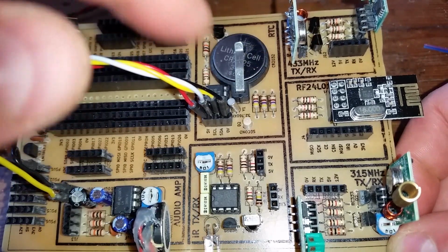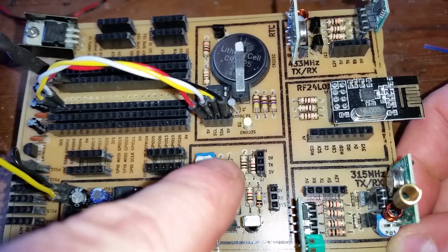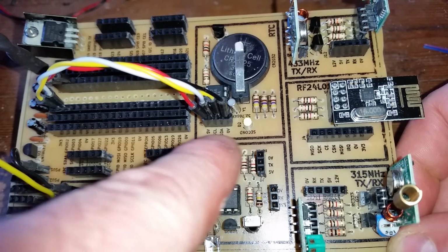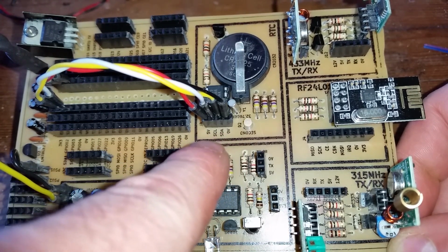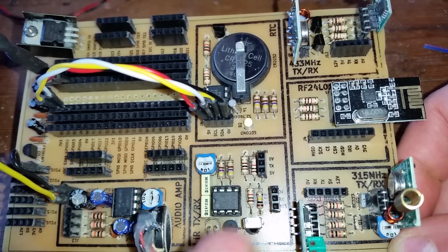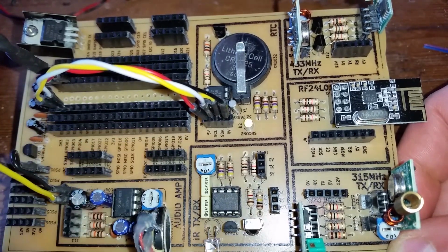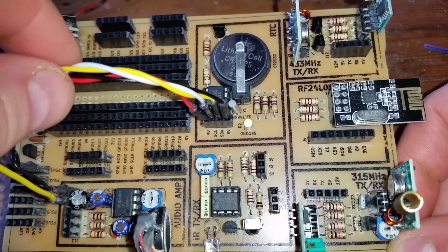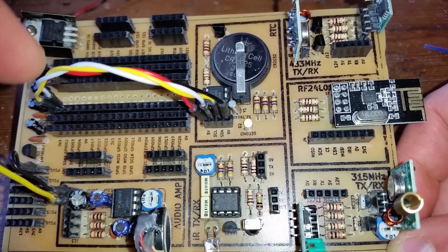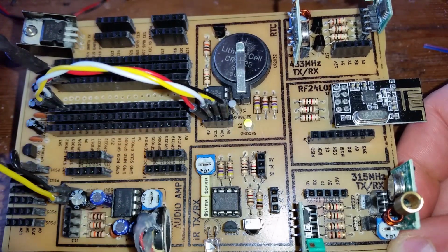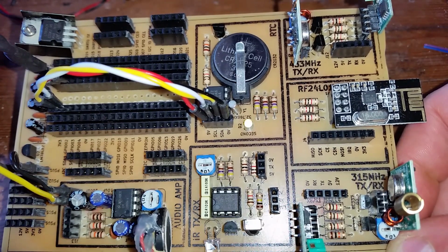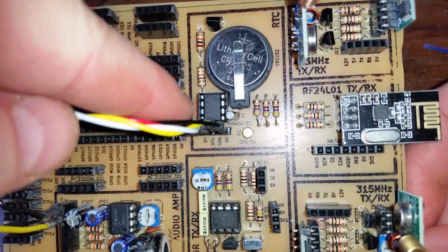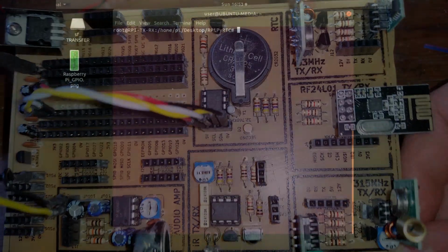The real-time clock part of this circuit only requires 4 connections: 5 volt, 0 volt, and some I2C connectors, a serial clock and serial data. And the serial data is bidirectional, which is why you only need 2 wires to communicate with this. And although I'm connecting to the I2C part of the Raspberry Pi, in Python I'll just be simulating the I2C logic to actually drive and read and write to that real-time clock chip which is there.